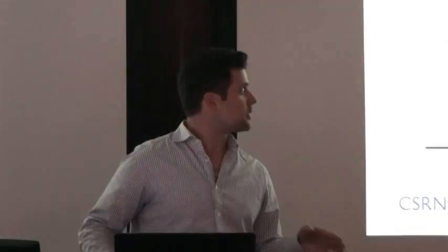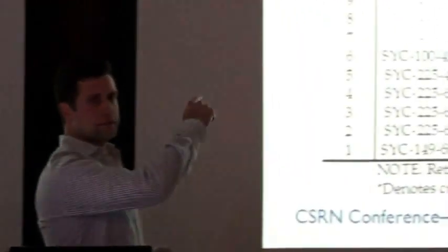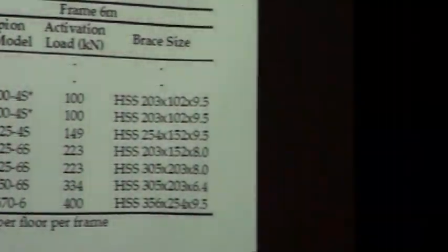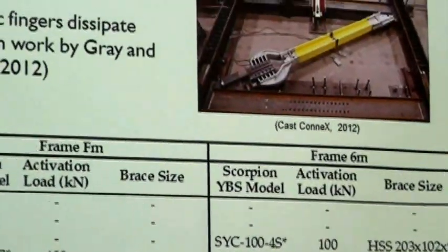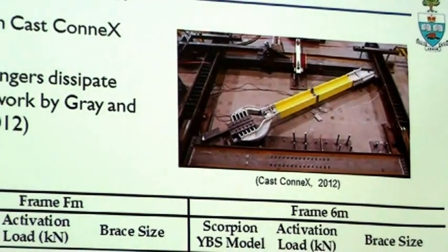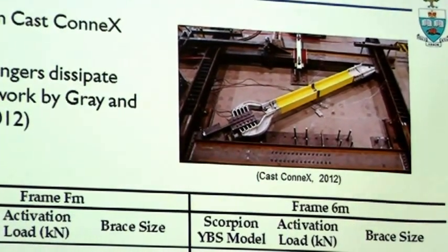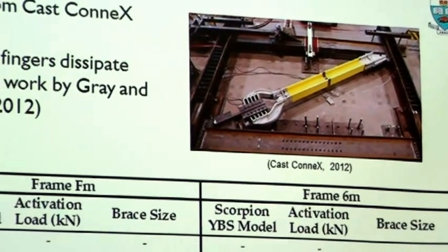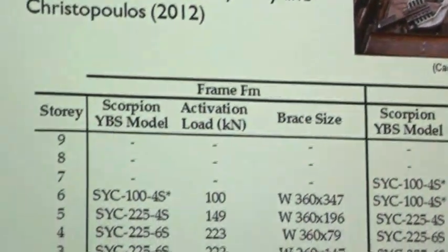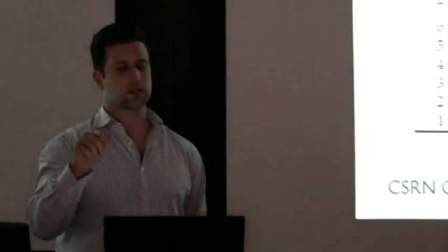Yeah. The thing about that, though, is that in fact, the stiffening is engaged at quite a higher drift limit than the 1% that I have imposed, especially for the design basis earthquake. For the MCE, my maximum inter-story drift, I believe, is around 1.4%, and that should still be within the more horizontal portion of the shape that it gives. But it's especially for higher inter-story drifts, so that's a definite concern.